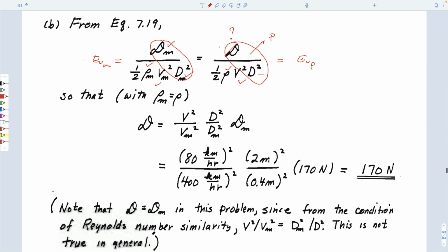So anyway, that's it. So dimensional, the inappropriately named dimensional analysis, which is really analysis with non-dimensional variables. But it gives an interesting way to be able to look at these fluid systems, and can be applied in any branch of engineering. You'll find that pumping test solutions for groundwater flow, pumping test solutions for petroleum reservoirs are all cast in terms of non-dimensional parameters, which would come out with exactly the same techniques that we're using here. So it's throughout engineering and science, this idea of using non-dimensional parameters is a key tenet, I think, that you'll see elsewhere in your careers. Okay?